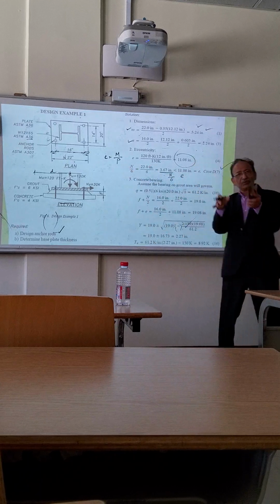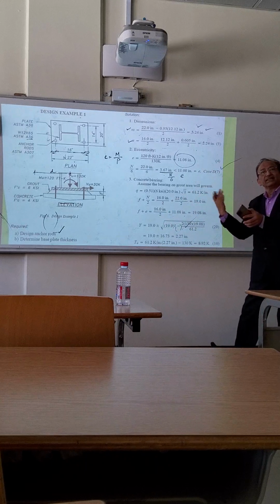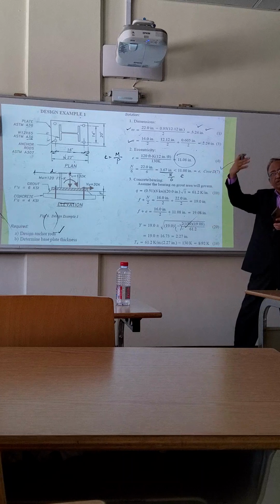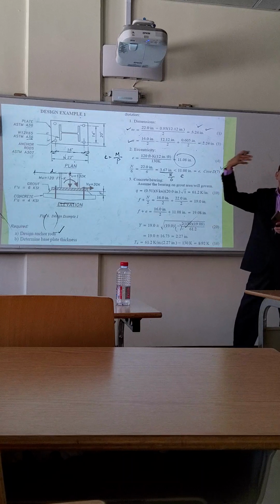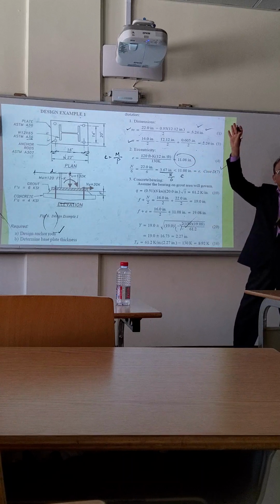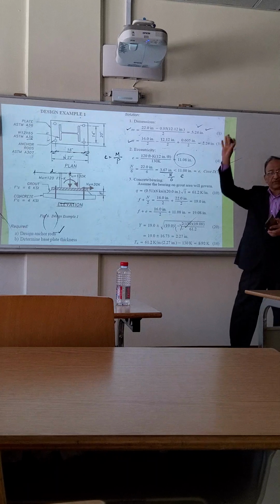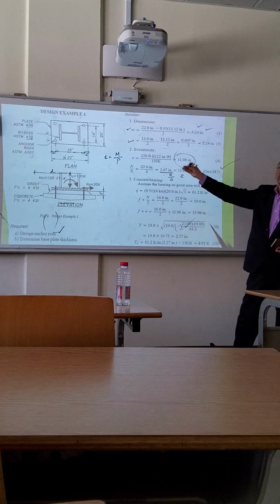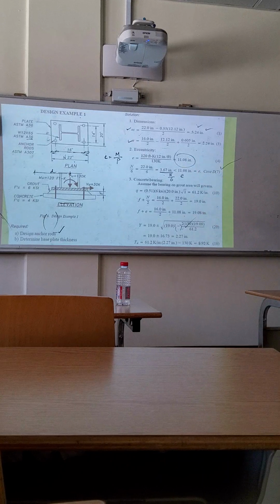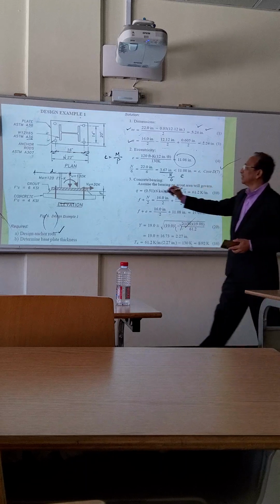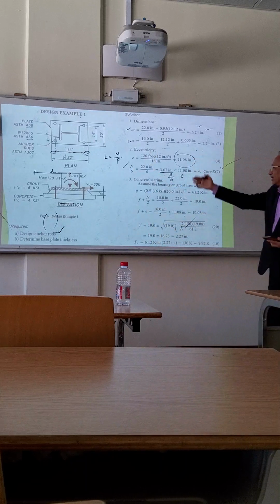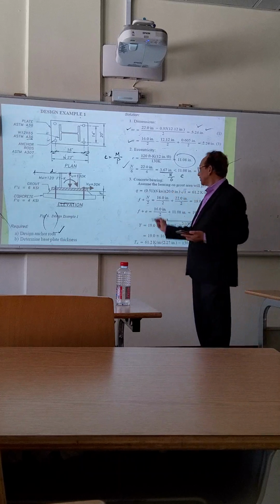If it is up to N by 6, it is case number C. If it is less than N by 6, it is case number B. If E is equal to 0, case number A. These are the 4 cases, and based on that, you will decide which formula you will use for thickness or the tension, all these things. So we decide first which case you have to use, and calculate accordingly.